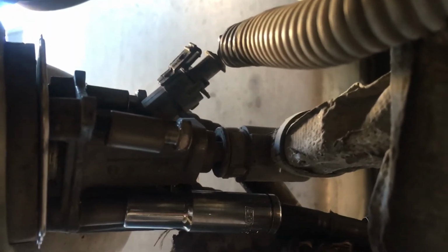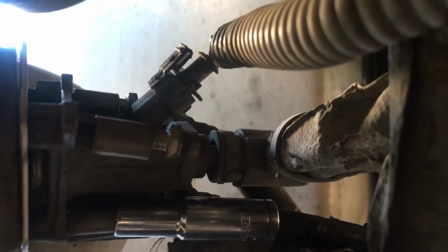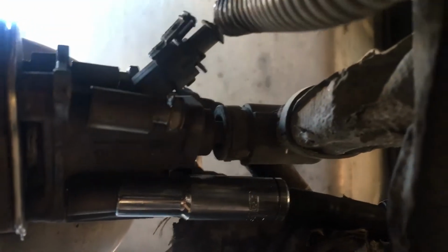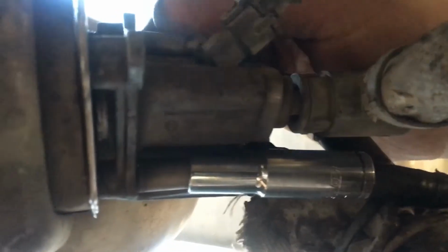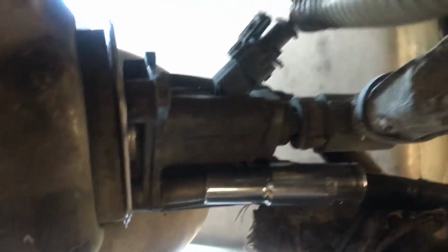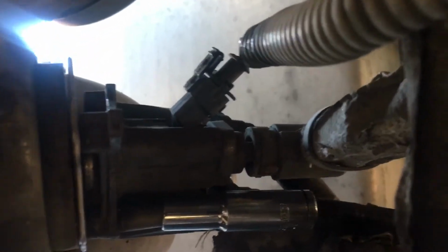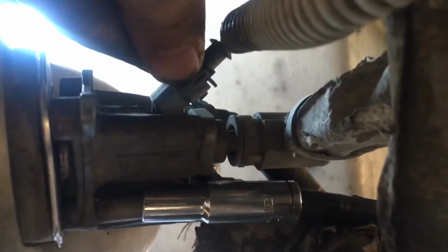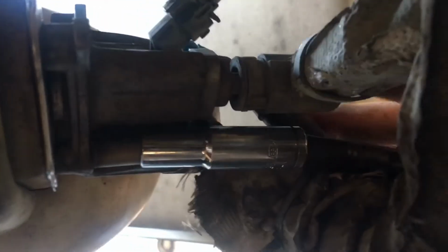So here's my DEF doser again, and what I'm doing is just removing the 3 mounting bolts here, in order to remove it from the decomposition tube so that I can put it in my measuring container and run the DEF pump override test. What you have here is the DEF dosing into this, the electrical harness giving it power, telling it how much to dose, and then your 2 coolant lines on the back.